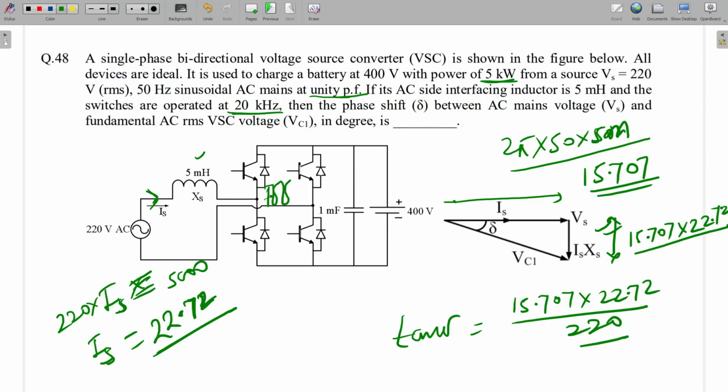So what will happen here? Some pole voltage will generate, a high frequency voltage. So how will power transfer? Here one fundamental voltage will be there between these two points. If we apply high frequency sine PWM, then what will happen? Here a high frequency voltage will generate, but that high frequency voltage will have a sine component. Okay, you are getting it. Okay, sir.